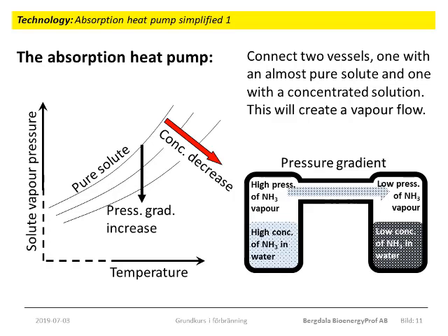Vaporization requires energy, while condensation releases energy. So there will be an energy transport from left to right, and the vessel to the left will cool down. With a closed system like this, an equilibrium will ultimately be established. So we have to avoid that equilibrium.